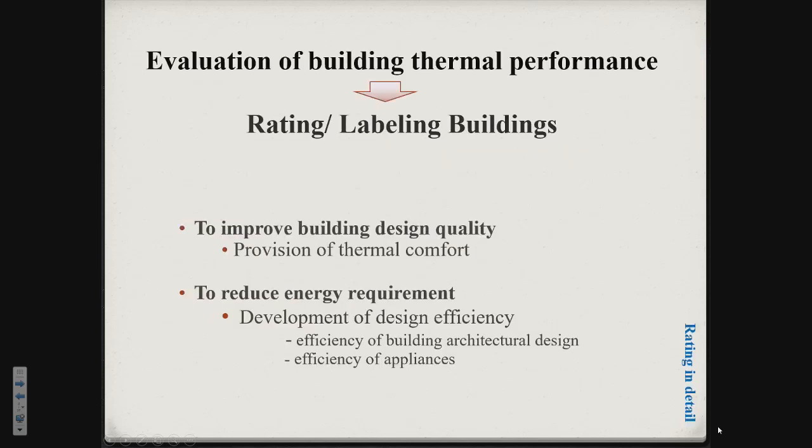The problem with the index that we are employing to evaluate the efficiency of a building is that, in this case, we consider the building conditioned, so its efficiency is more related to the efficiency of appliances. If we insulate the building without considering the climate, a well insulated building using the most efficient appliances gets the best result.